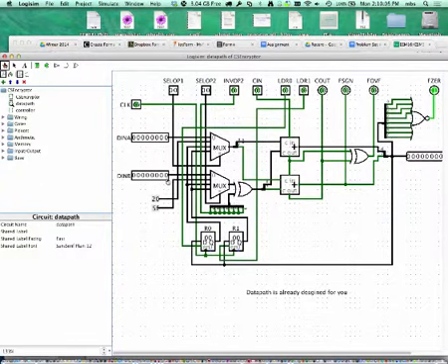And likewise for operand 2, it can either get it from D in B, which is a second 8-bit input into the data path, or it could be the constant 5f. 5f is actually 95, the number of printable ASCII characters you have. So you'll have to think in terms of modulo operations around this. And then finally, the other two are again R0, R1. The output of the adder can also be loaded into either one of these two registers or both of them.